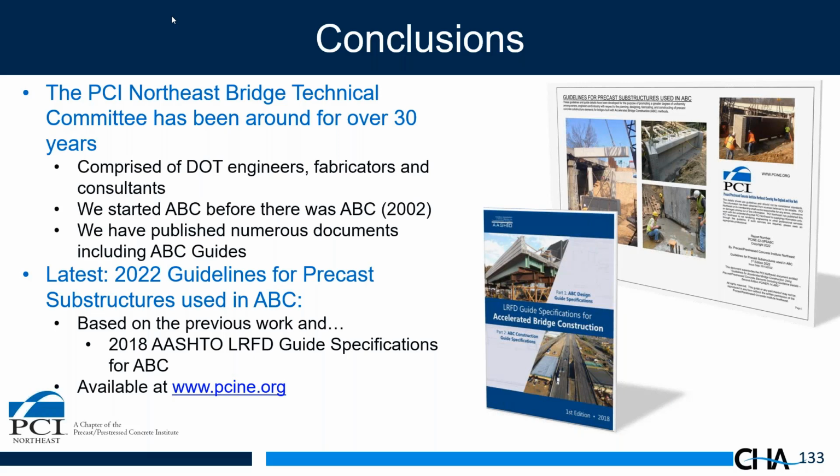What assumptions were made regarding lateral loading during development of connection details? Well, the key thing with any connection is you design it for the forces acting on it. And the AASHTO guide specification has provisions for designing for forces both axial, transverse, and longitudinal. A good example would be a column connection where you can have biaxial bending and axial compression. All of the provisions in the guide spec cover that, so it's basically the same as cast-in-place design. You can account for lateral loads as well as longitudinal loads, as well as vertical loads and shear.